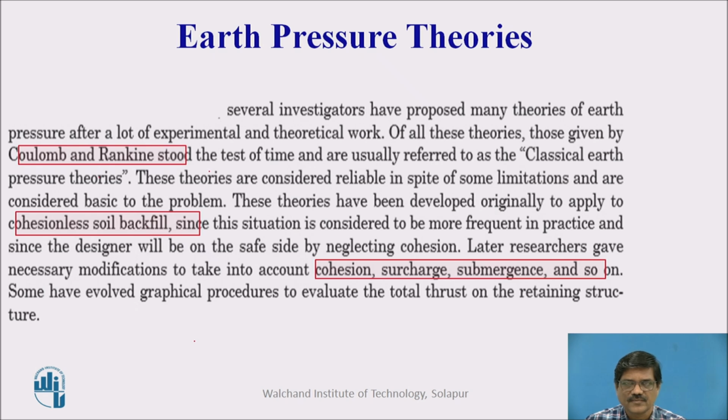These theories were originally developed to apply to cohesionless soil backfill. Since this situation is more frequent in practice, and since the designer will be on the safe side by neglecting cohesion, later researchers gave the necessary modifications to take into account cohesion, surcharge, submergence and so on, because at the time of derivation of the formulas these parameters were not taken into consideration. Later some researchers worked on this and gave modifications to the original equations where we can incorporate these parameters.